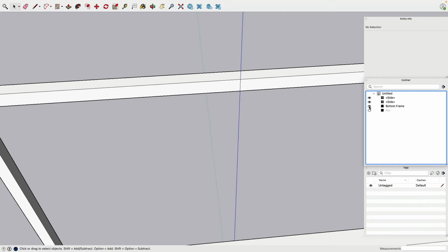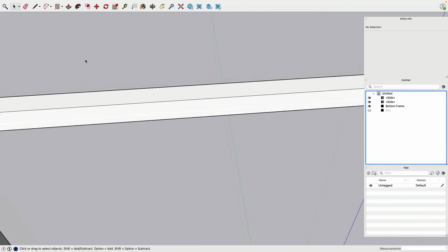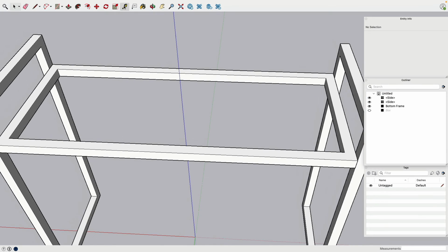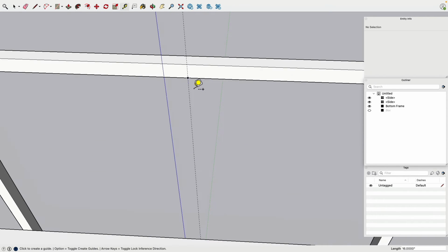Let me show you one time maybe a different way how we can do this. This is then basically all via the guideline again. So I find where's the midpoint. There. Okay. 0.5 to the right, 0.5 to the left. Very good. Rectangular drawing tool on this face.